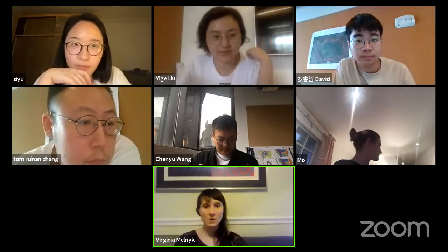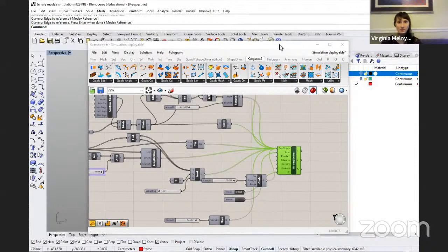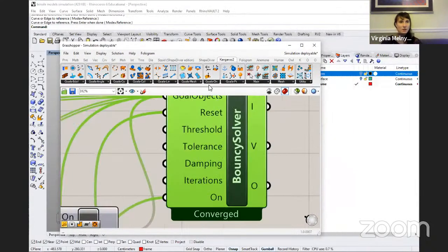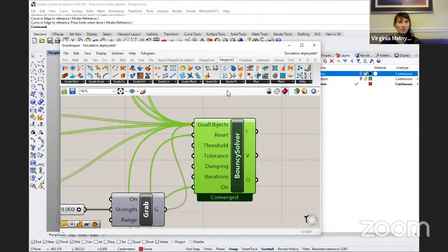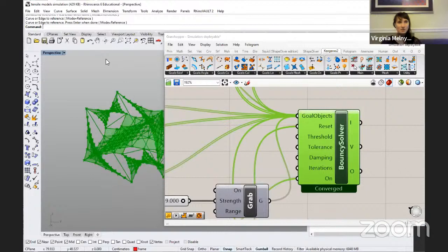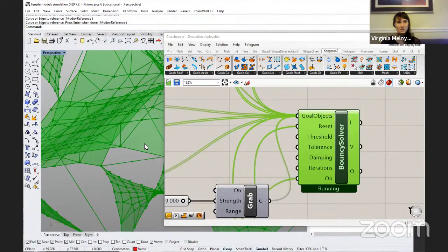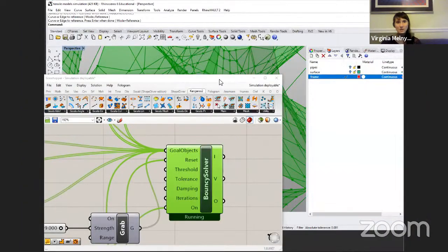So the first Rhino is the setup, and then I will bake this and create the knitting pattern from this one. I think you have to pull out the parts, because if you just bake this, it's going to bake the whole entire thing with all the points and stuff. But you'll want to find which one is the surface and just take the mesh, and this is what I would use for the pattern, not the original file. So that's why I have some extra layers. Okay.